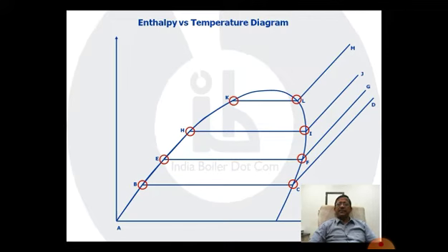It is a little different from the temperature entropy diagram which we are more familiar with. The look is like this instead of that typical hump of the temperature entropy diagram. Several things can be noted from this diagram. One is that BC was the latent heat on this pressure line, which is EF on the higher pressure line, and HI on the even higher pressure line. So as the pressure goes up, the latent heat part keeps going down.